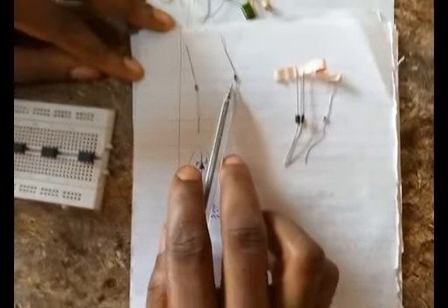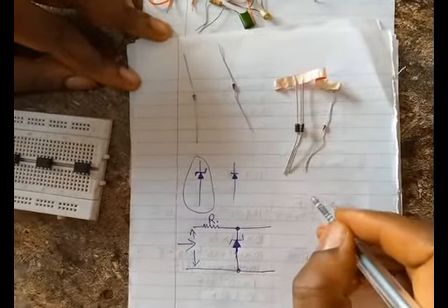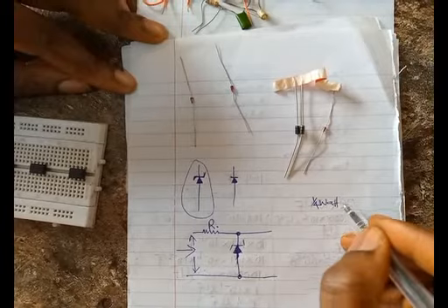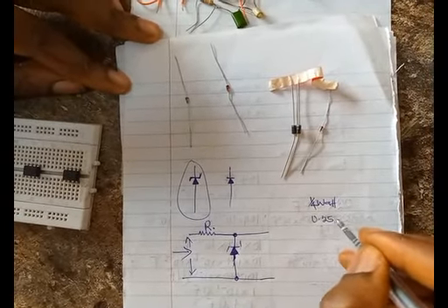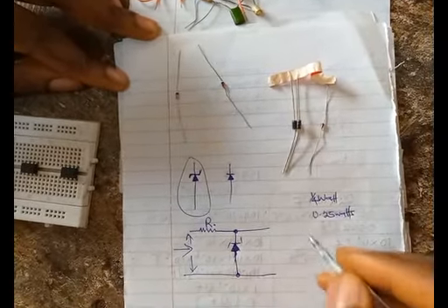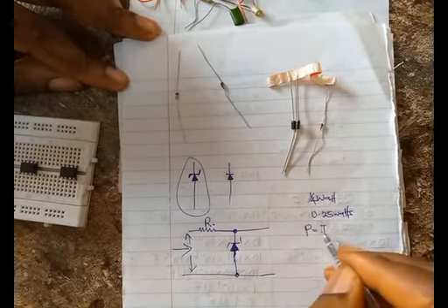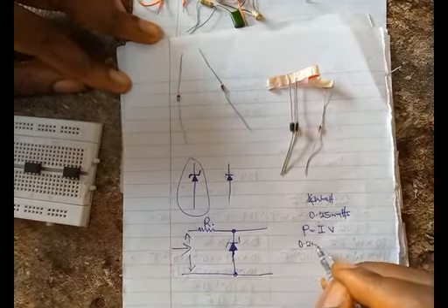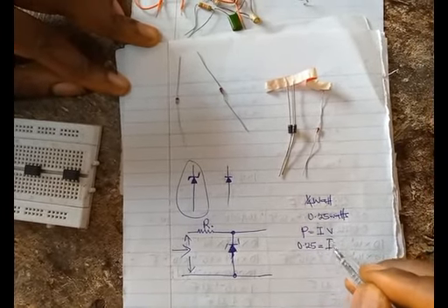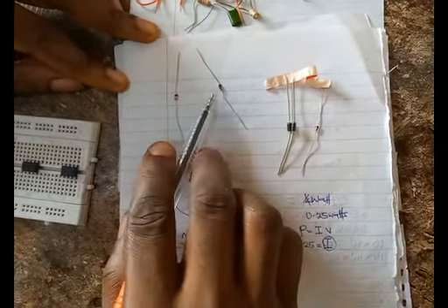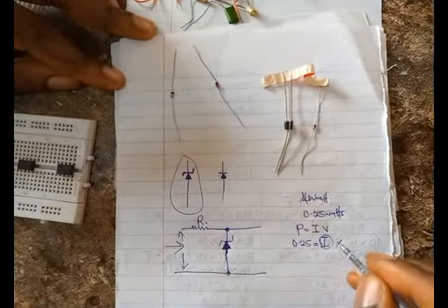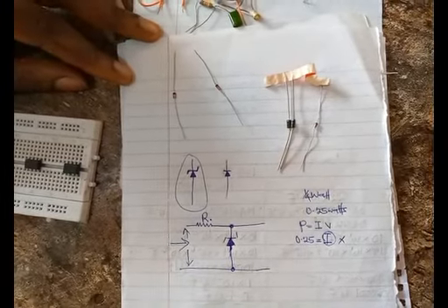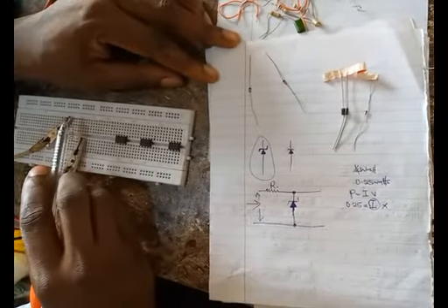This particular one I have here is a 1/4 watt Zener diode. 1/4 simply means 0.25 watts, right? And we know that power is IV. So if it is 0.25 watts, then how much current can this Zener diode handle times the Zener voltage? So now I'm going to be using maybe a 5-volt Zener diode as an example.